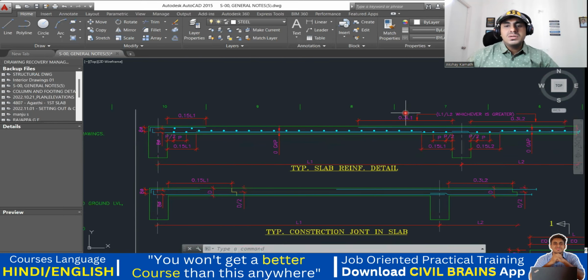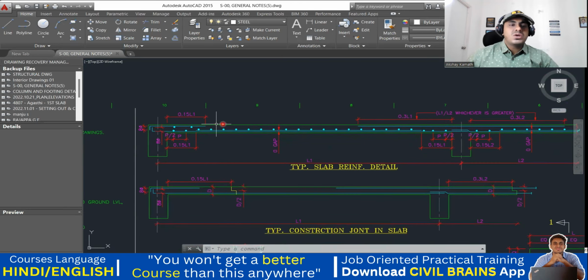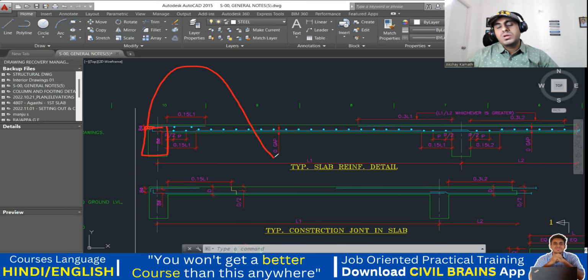That's it. Again, another question. I don't know whether I explained to you or not. Why is this 0.15 into L? Why is it not 0.3? Because here, anyhow, you are giving 0.3, but why is it stopped at only 0.15? The reason is very simple: for this particular slab, we have only one beam in this direction. So because of this small fixity, a huge bending moment will not occur, or the intensity of the bending moment is not too much.